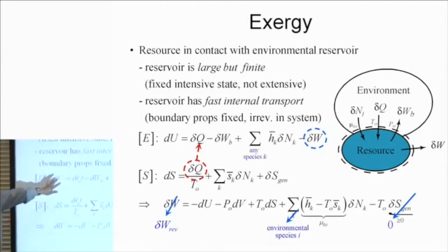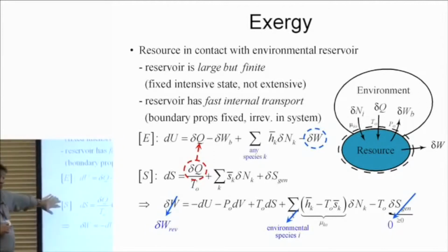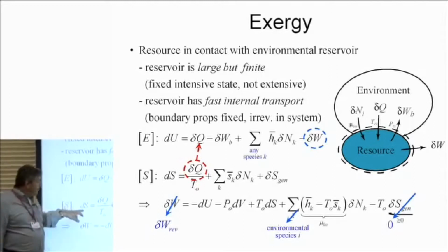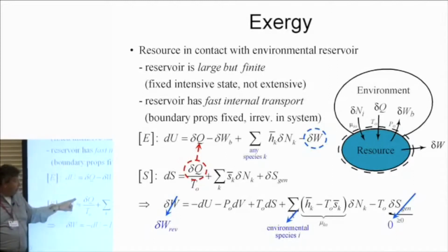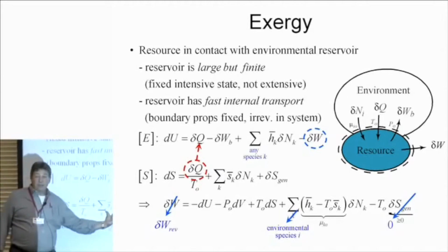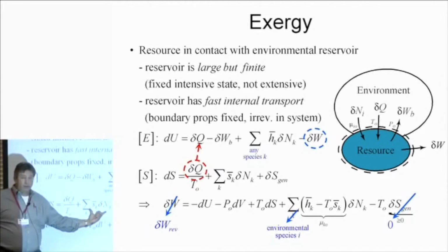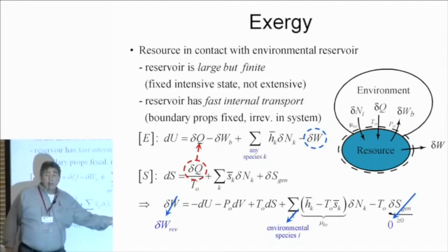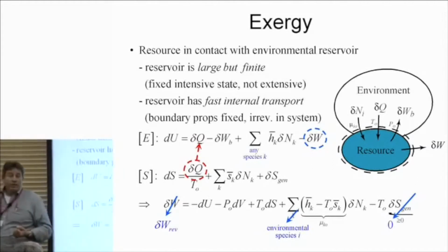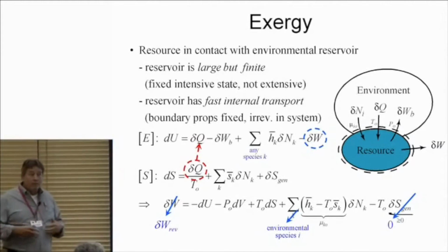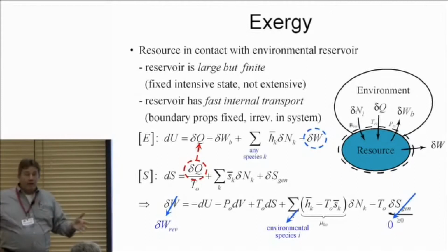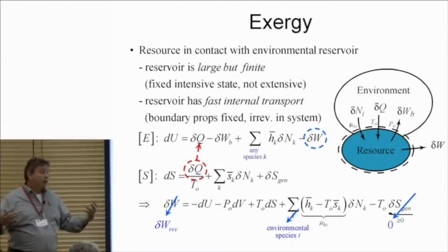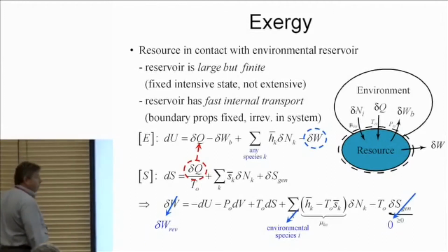Okay, and for any species, if I do an entropy balance for this, the change of entropy inside the system goes up due to heat transfer, an amount delta Q over T, the temperature of the boundary, goes up because matter comes in and it carries entropy with it, so that's S bar per mole times the molar transfers for the species. And I can make entropy inside. So if I do something that causes my energy to become less organized, have more rearrangements, I burst a diaphragm inside and let it double its volume, unrestrained, that generates entropy, more rearrangements in the system. Okay?